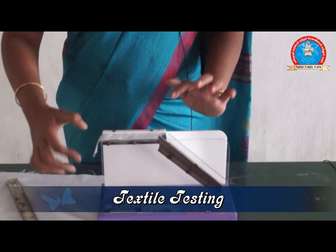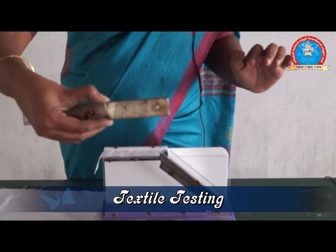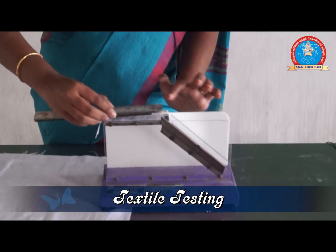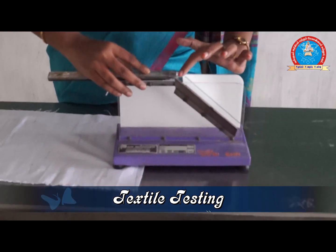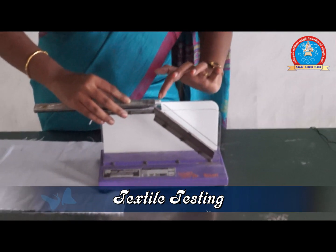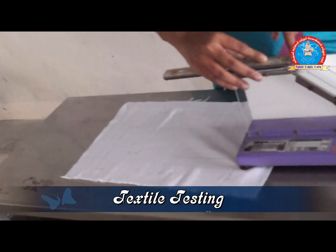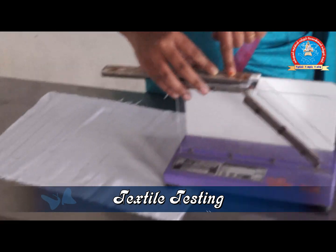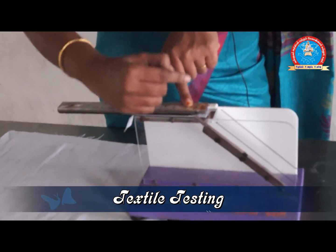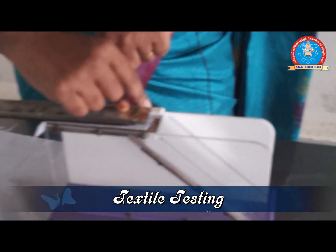After placing the sample on the platform, we place the bending scale on the fabric like this. Both should meet at the same point, the datum line. The bending scale and fabric should both be placed to meet this datum point.